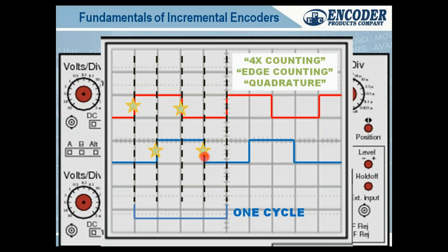Encoders cost more as well. As you increase the resolution on the disk, it costs more to print that disk because they're finer lines. And it also requires tighter air gap spacing. It's more to manufacture them. So when you buy encoders and you go up in resolution, you go up in price. So it's a way to save on the cost of the encoder and the machine design as well.